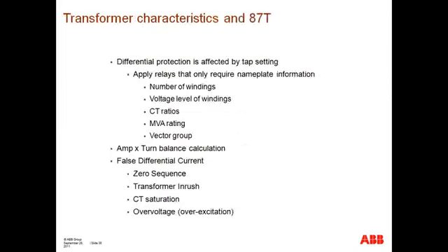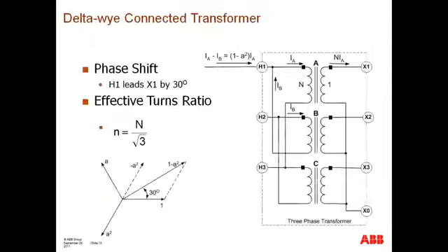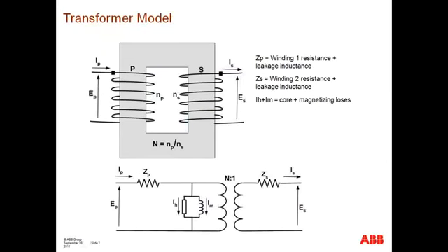Inrush current. So when looking at inrush, I'm actually going to come down a couple of slides to provide you with this explanation. If we take a look at this basic circuit model, the concern is, and I'll explain it in a very practical way, okay, imagine that you have a source connected on this winding right here, and there is absolutely nothing connected on this winding right here. If you close into this particular winding, although there's no load connected here, you have this magnetizing branch through which current is going to flow. That, in essence, is your inrush current, which, if we look at the way we apply our differential protection, there's going to be current that's going to come through winding 1 CTs.